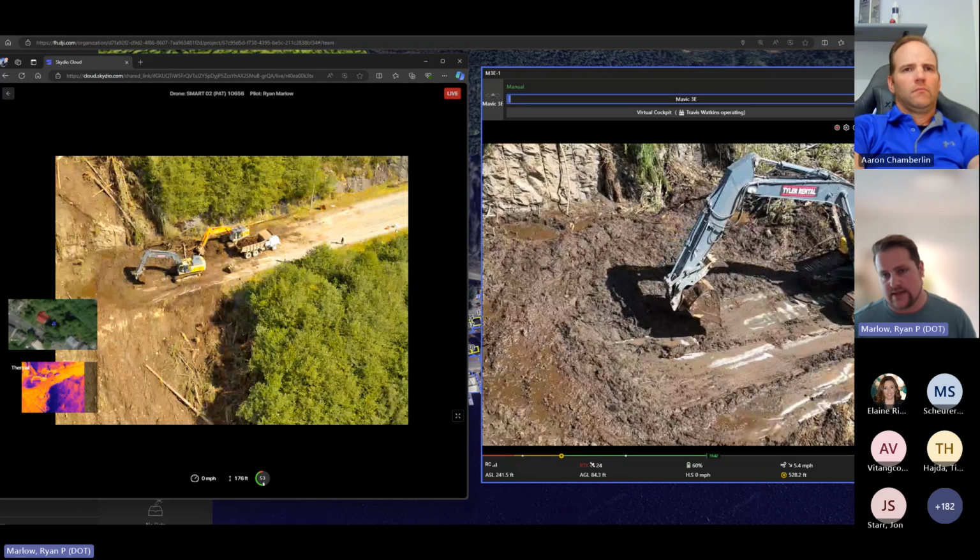So normally what we see is we'll show up on site, we'll grab a rapid image process of the entire environment. And then from there, we have secondary teams that are taking that data and saying, all right, we're going to drop ground control here. We have a core station here. Here's the mount point. Here's everything else. So that live stream nature is basically allowing for us to then dictate, hey, here's the collection area that we're going to capture for this next high-res scan.